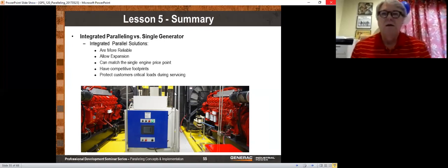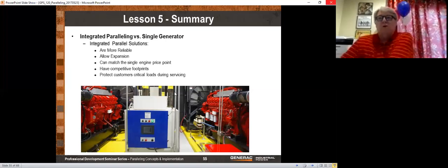Yeah, that design is very common. In fact, a lot of times when you have small facilities and small generators, it probably doesn't make sense to go the paralleling route. The smallest natural gas generator that we make as standard to parallel is 100 kilowatts. The smallest diesel generator is 300 kilowatts. We can make generators smaller than 300, but a 200 kilowatt parallel generator is about the same price as a 300. So if you have smaller generators, you may choose to go that route